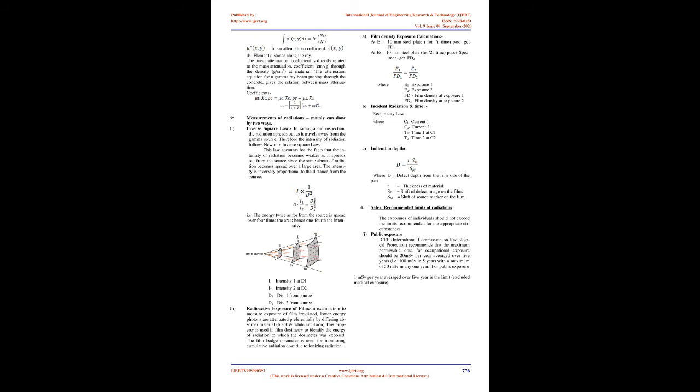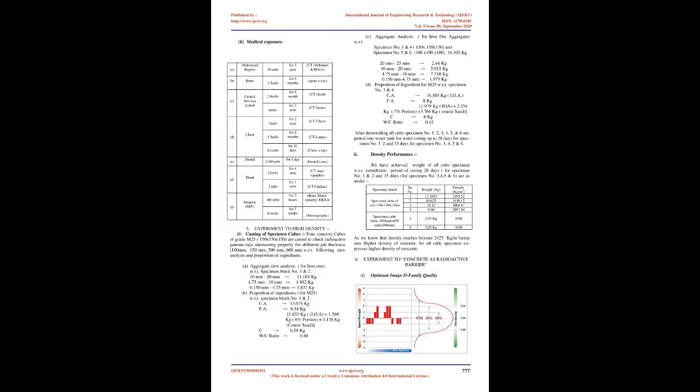Property of concrete/aggregate. 1. Neutron shielding property. Example: radiation shielding concrete. The shielding properties of this concrete against neutrons is being used to build bunkers, mazes, and doors in medical accelerators. The objective was to characterize the material behavior against neutrons, and test alternative mixes including boron compounds in an effort to improve neutron shielding efficiency. The original mix, which includes a high fraction of magnetite, was then modified by adding different proportions of anhydrous borax, Na2B4O7.